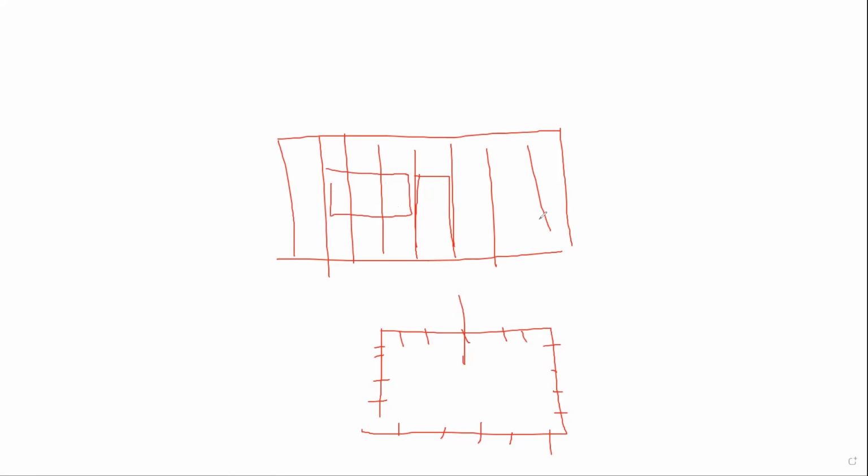You follow? So in general, your stud wall is spaced at 600, because like I said, you start with a spacing of 600. Now, you design the stud wall, and normally your stud wall should end up being a 2x6.